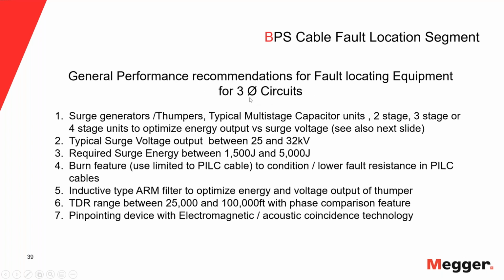It's a totally different issue with paper cable, because paper cable has oil in it, and I need to lower the fault resistance so I can thump it. That means I have to literally burn the oil and make carbon from the oil. Carbon has a lower resistance, so I can thump the fault. So burning is a good feature when I have paper cables.